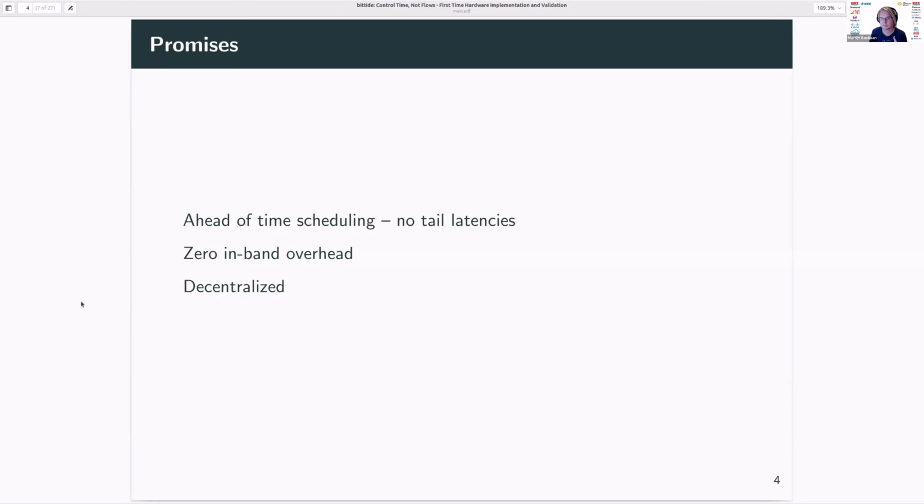We don't hierarchically derive clock signals, and each node in the system is basically self-contained and can operate independently. Above all, it is simple, both in its theory, there are no complex state machines and synchronization protocols, but also in its hardware implementation.